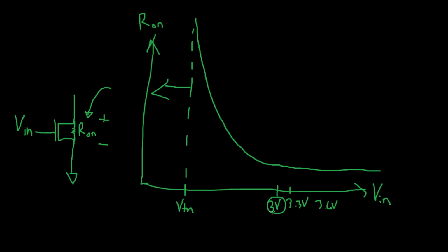This is the reason why semiconductor manufacturers always show this value in the datasheet and they leave the nominal value out. They're trying to show you the worst possible case, and if you use the number for RDS on from this, then you're going to definitely design your system to work correctly.